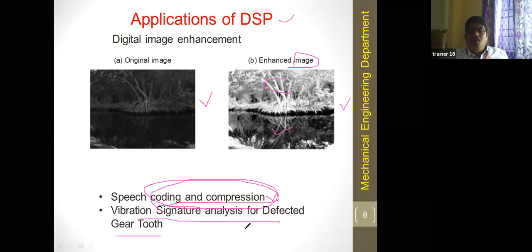So in the gear tooth, if you observe, sometimes a particle from the gear tooth is broken, it's minute. So what happens, we can get more vibrations when it is running, right? Here the two gears are meshing together. Due to continuous running hours, the gear tooth gets damaged, and more small particles come off.